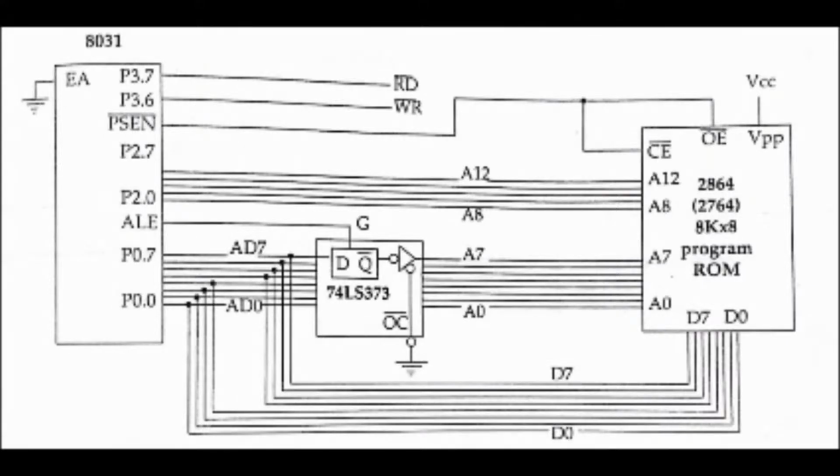The next step of the project is to fetch opcodes from the external EEPROM. Here in the diagram, we have shown the interfacing of the 28C64 EEPROM chip with our microcontroller, the AT89S52. The microcontroller is based on the 8051 architecture and has multiplexed address and data lines which are available outside for external use.